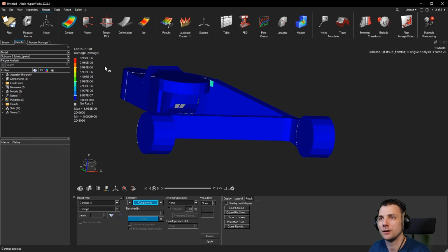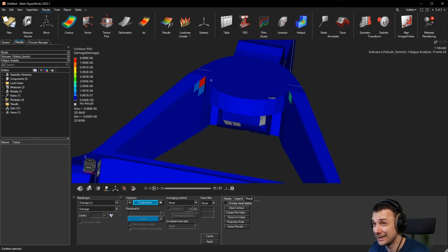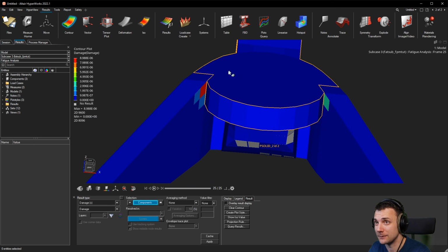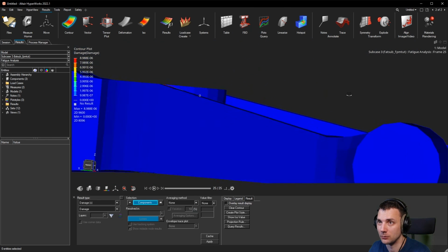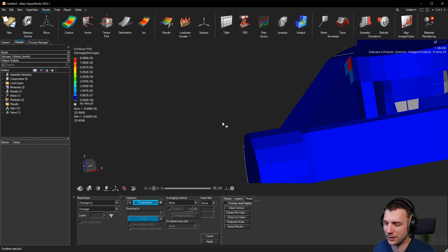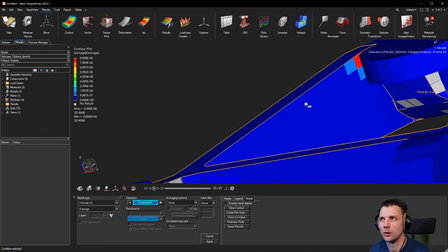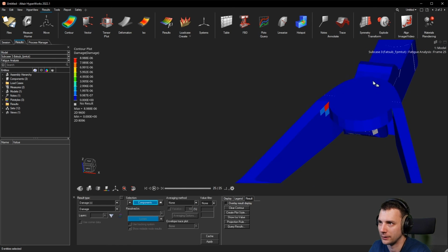What I would suggest is, I don't know, but mesh quality? I really would want to have that with a finer mesh to be able to see more of the stress, to be just able to have more precise stresses. This is one thing I would comment on that, but sure, that's just a tutorial thing here.